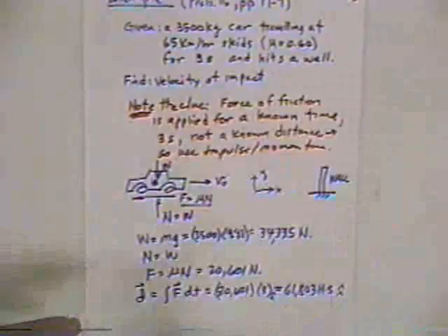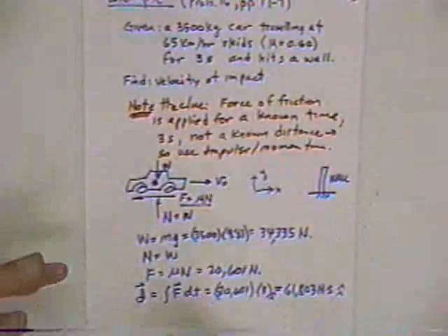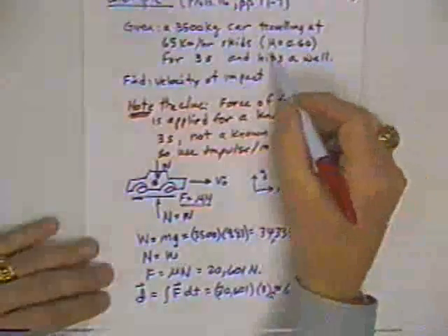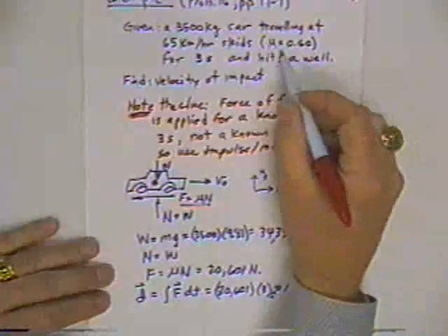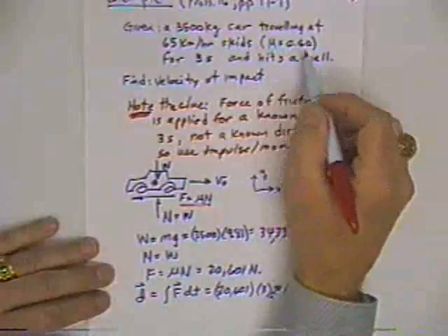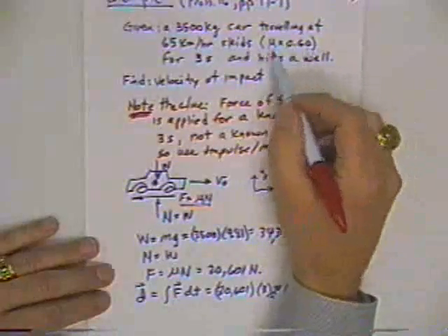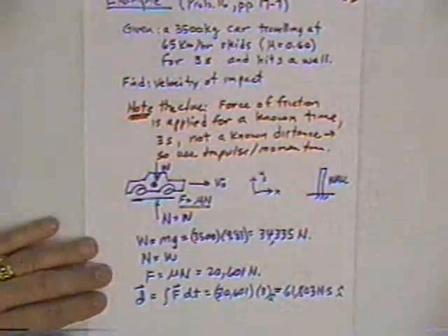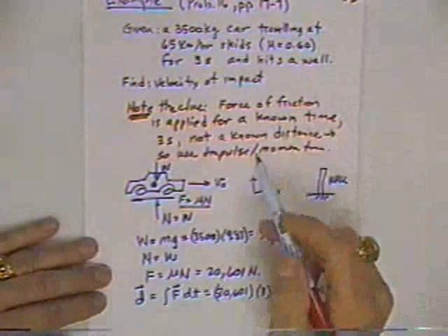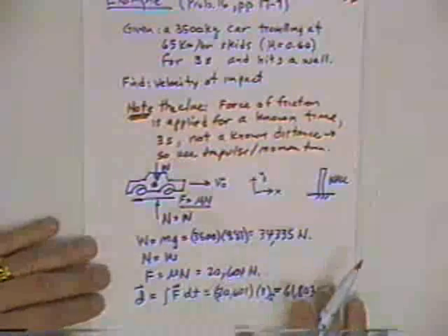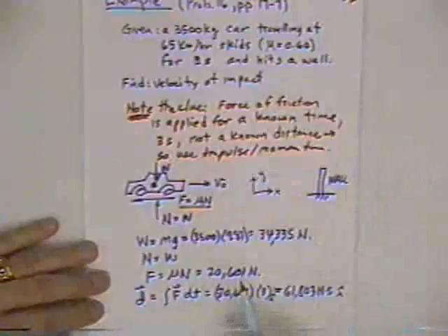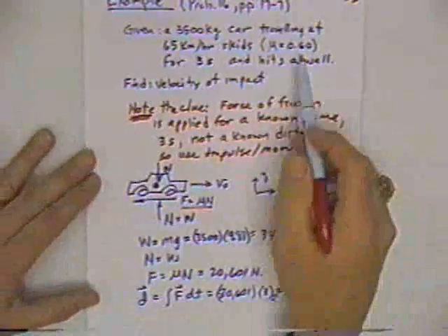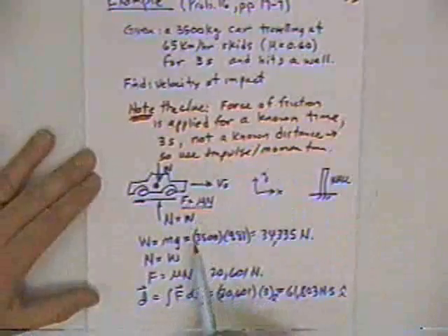So if you operate your brakes in the optimal way, the wheels are still turning, not slipping, just at the verge of slipping, you can get frictional braking forces that are higher by the ratio of mu static to mu kinetic. So maybe you get 70% instead of 60% of your normal force on those wheels as braking action. And that's one reason you try not to lock your wheels up. That's why anti-skid brakes are, well, the more important reason is you have better control if your wheels aren't locked up, but you do have better braking action.